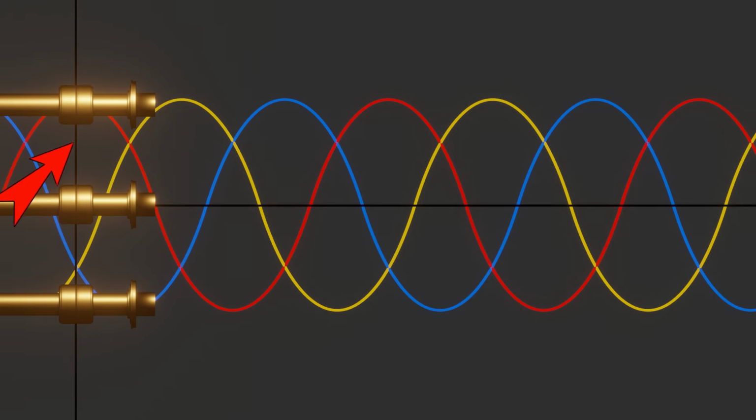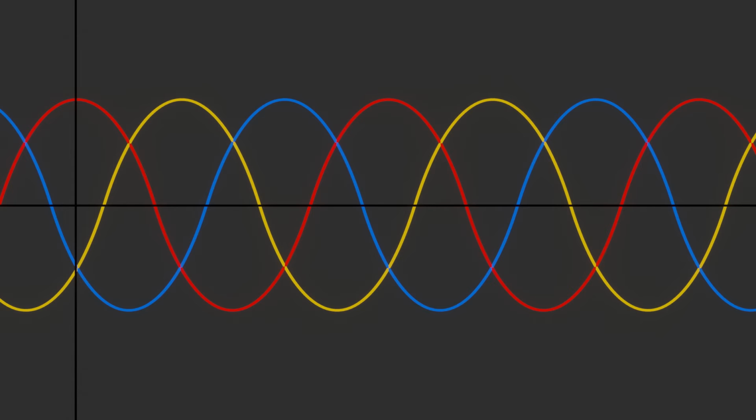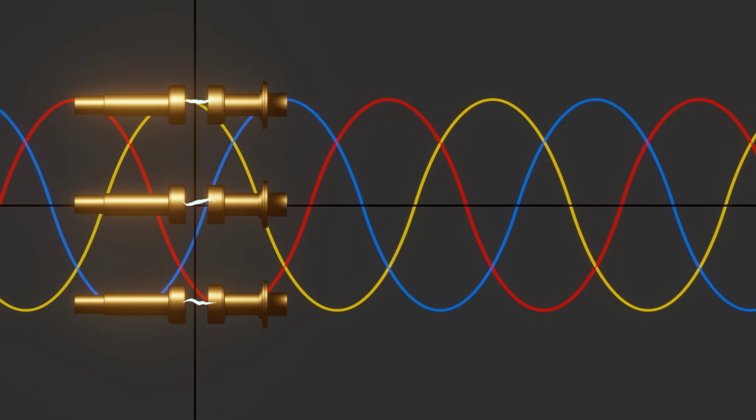Now, let's say at a certain moment, the circuit breaker initiates the opening operation. Suppose, at a certain moment, all three poles of the circuit breaker open simultaneously since the circuit breaker is gang operated. However, at that instant, arcing continues in each contact gap, so the current continues to flow through the gaps. Let's now consider the red phase for better understanding, and then we'll discuss how current is interrupted in the yellow and blue phases one by one.